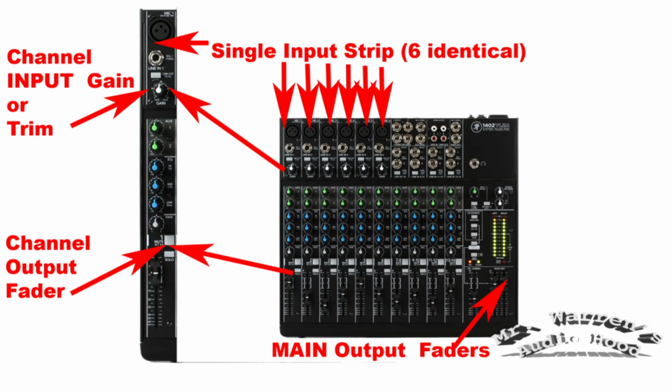Now, the next thing we'll discuss is how to actually set proper gain structure within your mixer. When dealing with simple basic mixers like this, the best thing to do before you hook any speakers up to it or have any amplifiers on or connected to it is to work on the gain within the mixer. The safest way to do this is to do this before you've hooked any amplifiers or powered speakers or anything like that to the mixer. At this point, you simply want to work on the gain staging within the mixer so you have a clean starting point.